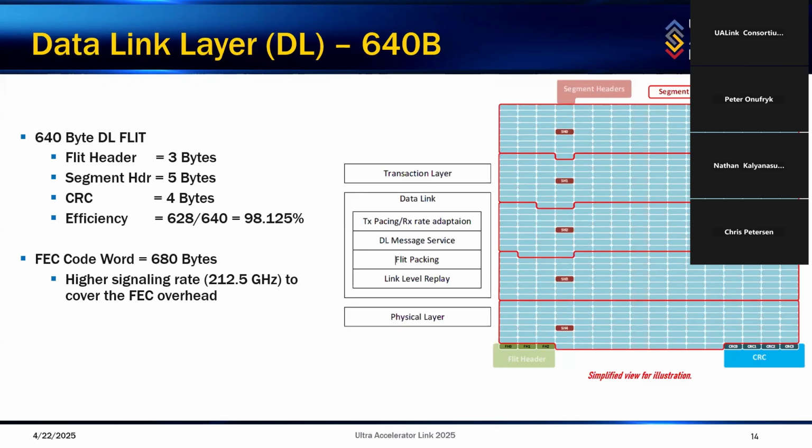DL also provides a reliable transport through link level retry support. In addition to that, there's port level reset, station level reset, and a few other RAS features which are supported through the DL. DL also provides a UART-style messaging service between link partners. UART messages may be used for in-band queries, key exchanges, and other services via firmware.